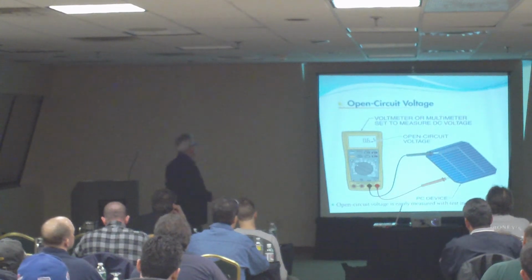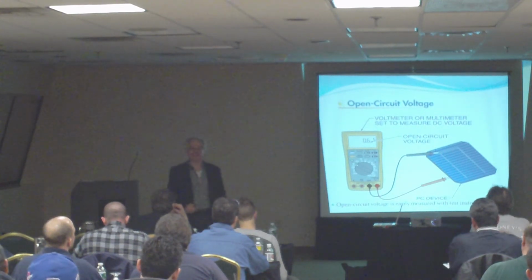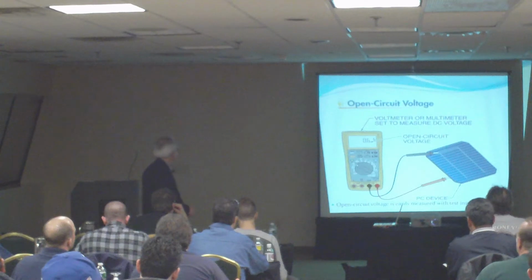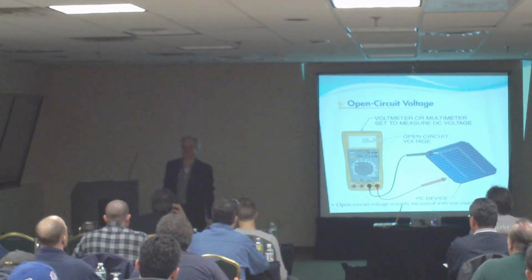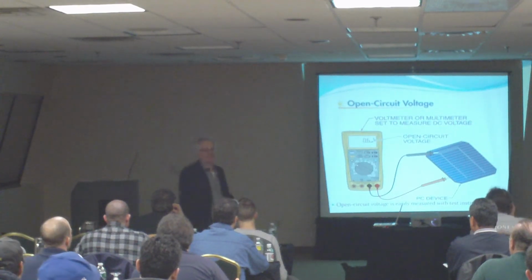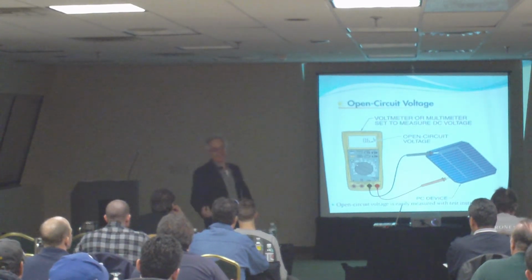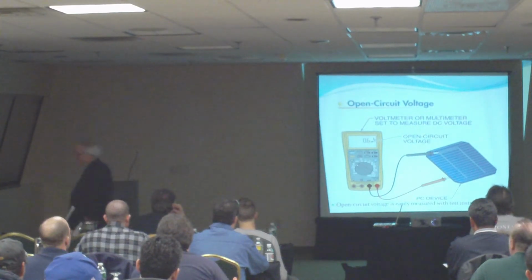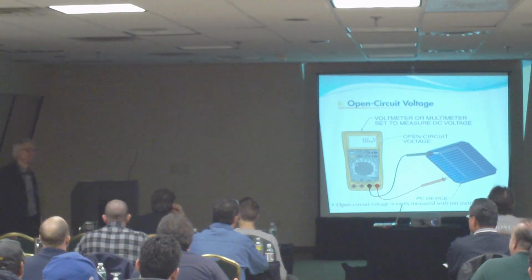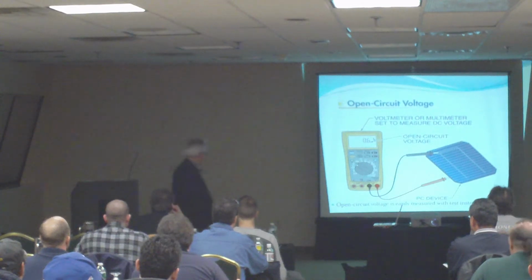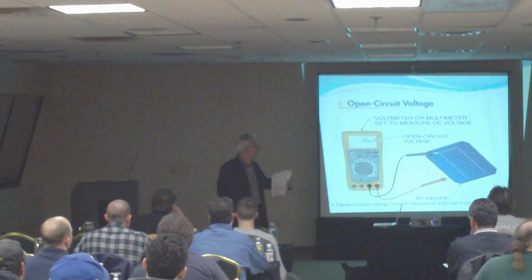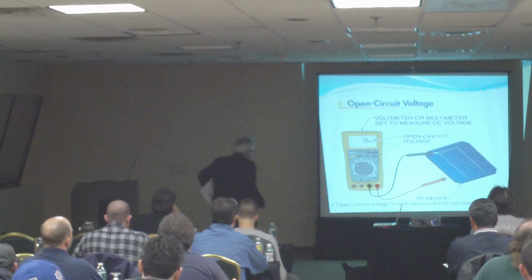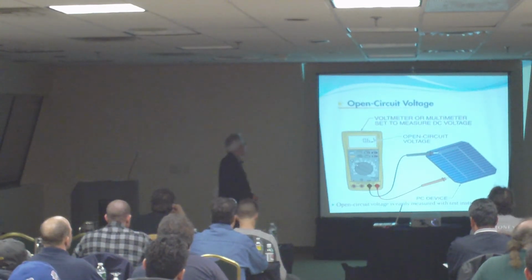Is the polarity an important consideration? Why? What happens if I reverse the leads and measure voltage? What is that going to tell me? What's the difference between a negative 6 volts and a positive 6 volts? There's no difference. It's just the convention, the way you measure it. Okay. So this is clear how we're going to measure.